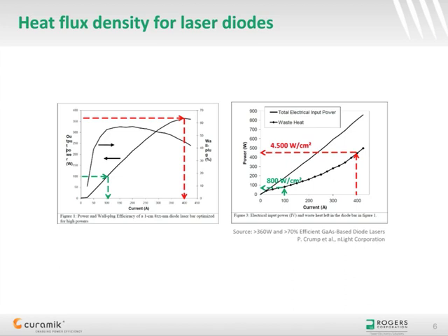In any case, driving a high-power diode laser bar inevitably means a large amount of heat and current is concentrated in a very small area. Take a look at the green arrows. For 100 watts of optical output power, 80 watts of waste heat is left in the diode. As the surface of the diode is 0.1 square centimeter, this means 800 watts per square centimeter.